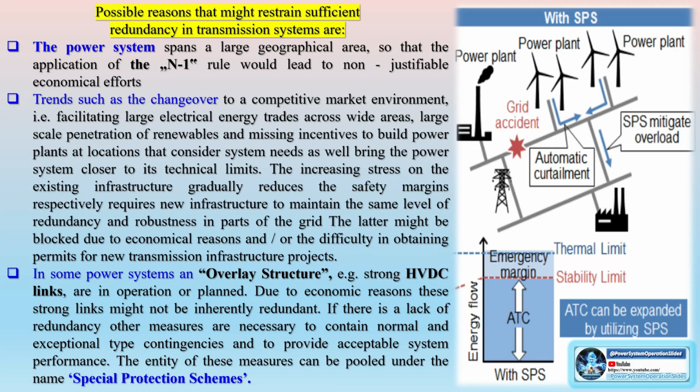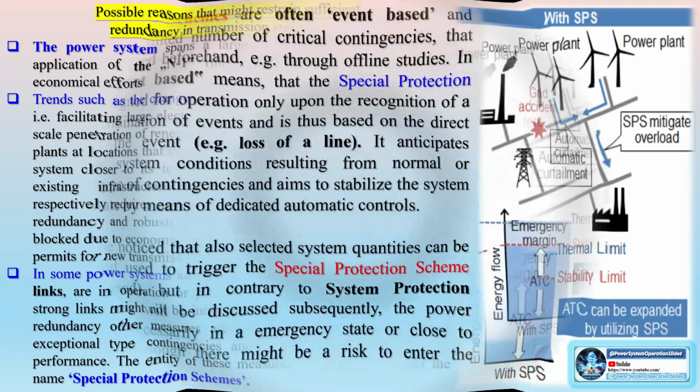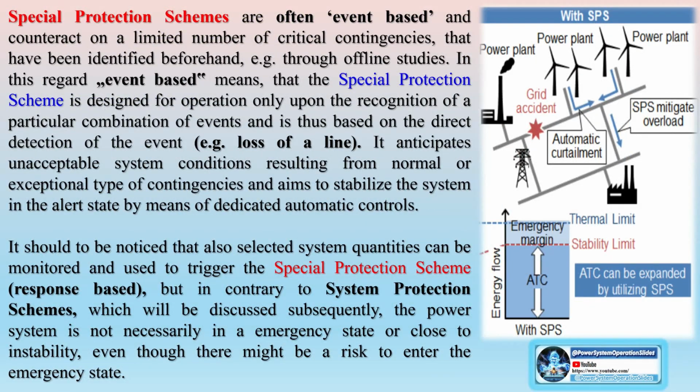Transient angular instability is the inability of the system to maintain synchronism. Preventive measures include braking resistor, employing FACTS devices, reducing the mechanical power driving the generator, fast valving, disconnection of the generator, etc.